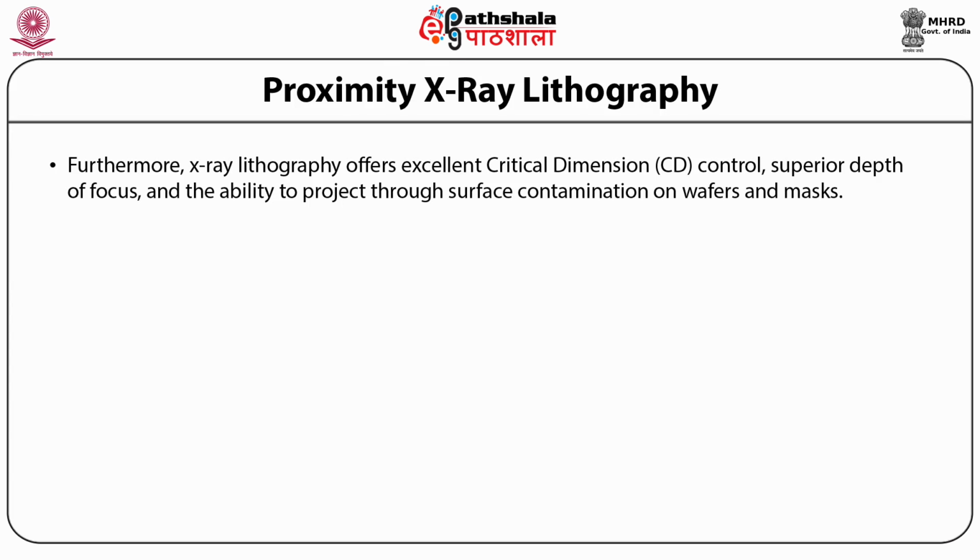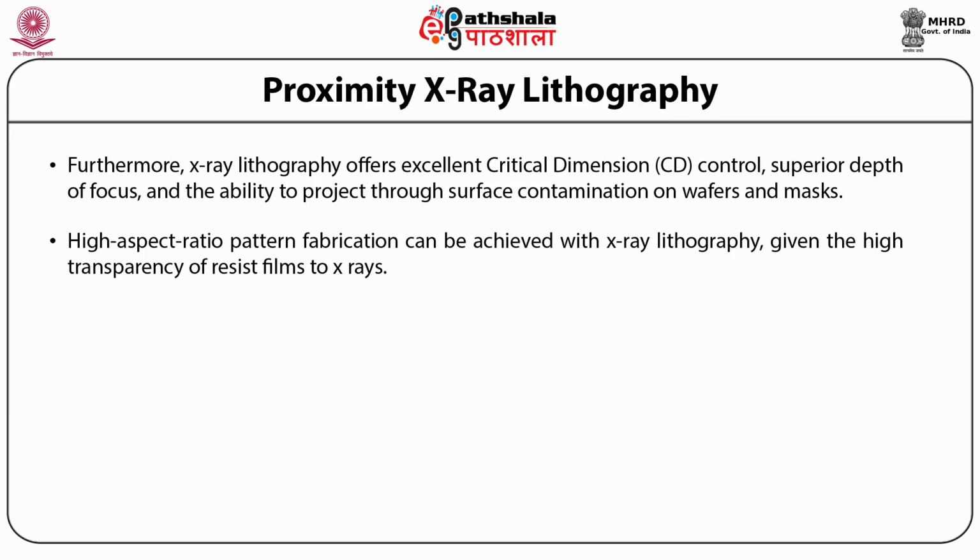Furthermore, X-ray lithography offers critical dimension (CD) control, superior depth of focus, and the ability to project through surface contamination on wafers and mask. Also, due to the use of resist films highly transparent to X-rays, high aspect ratio pattern fabrication can be achieved. And so there is no restriction on the field size.